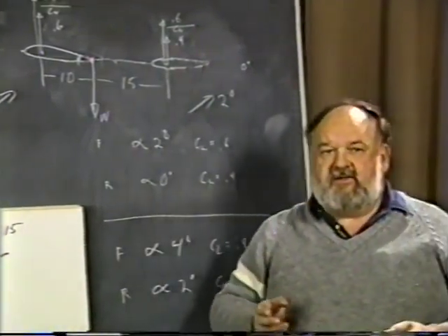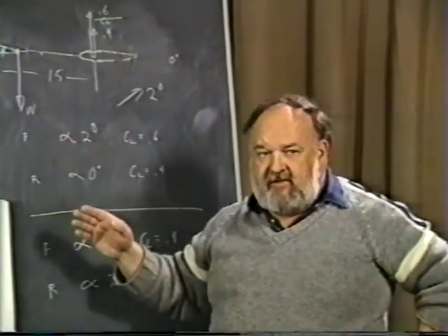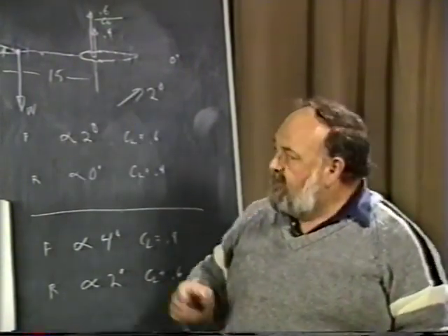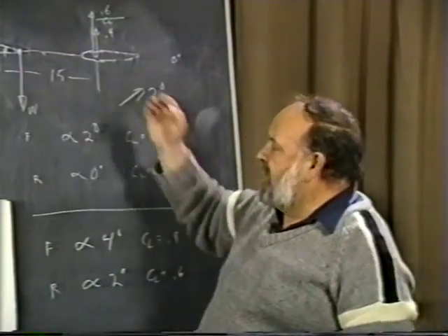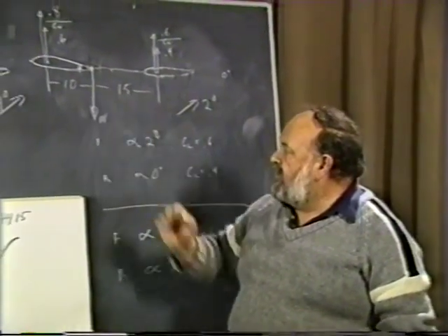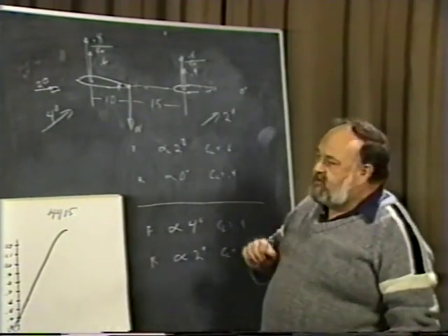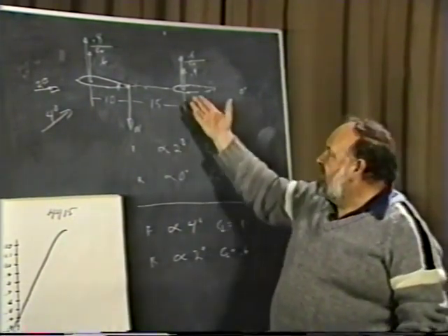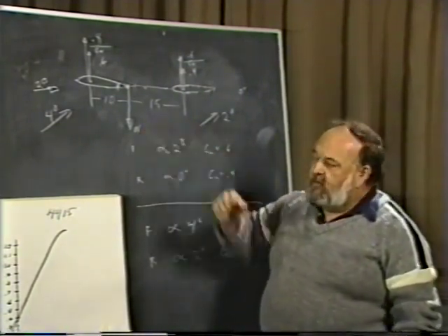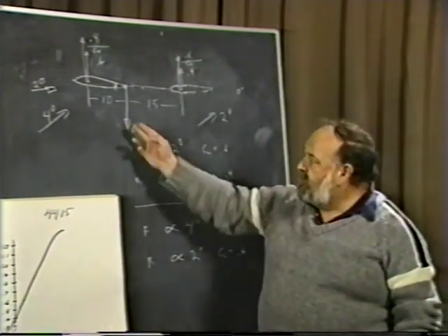This condition is somewhat sensitive for longitudinal stability, because as we change the center of gravity, you can see what effect this has on the loading on the tail. If we go back to this example again, where these two surfaces were identical, and for whatever reason we had to move the center of gravity further forward, well, immediately, to keep the airplane in balance, we would have to reduce the incidence of this. We'd have to let that same size wing lift less than it does. And the further we move it forward, the more it would have to be reduced, down to the point where maybe it wouldn't be lifting at all if we moved it all the way forward,